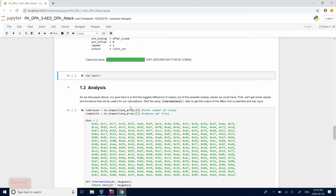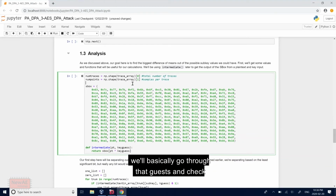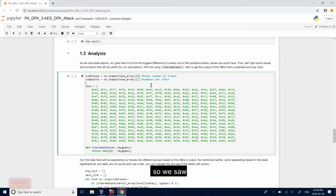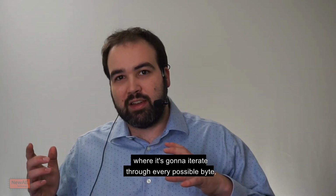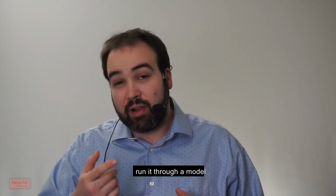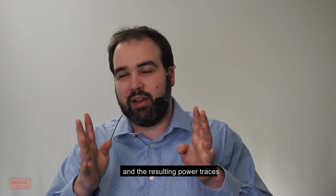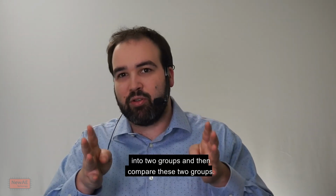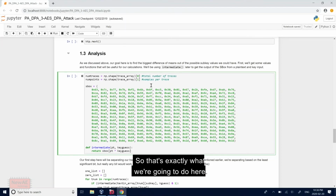So we have enough traces. What we'll do is basically go through that guess and check. We saw in the slides, there's this guess and check idea where it's going to iterate through every possible byte, run it through a model, and try to separate possible values of the key and the resulting power traces into two groups, and then compare these two groups. That's exactly what we're going to do here.